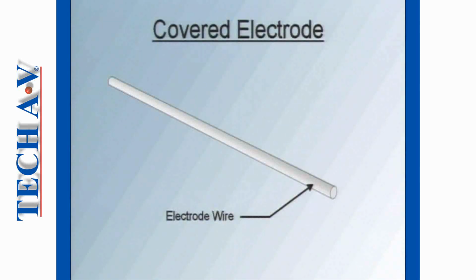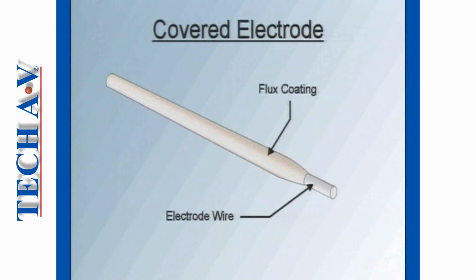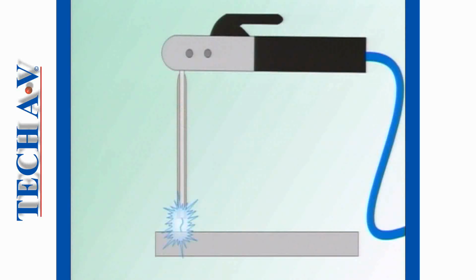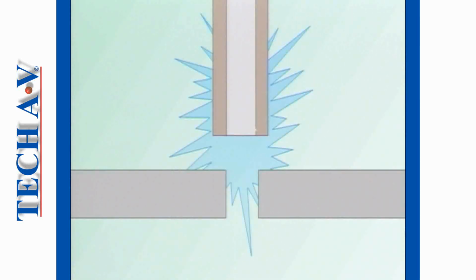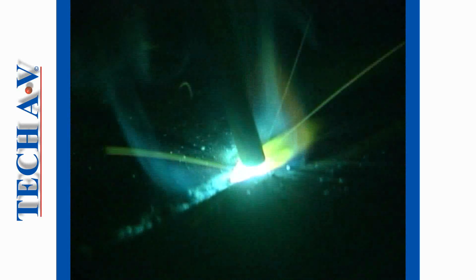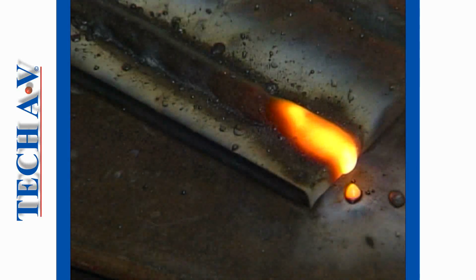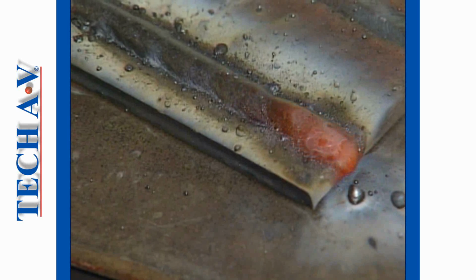An electrode is simply a length of steel rod, called wire, that is coated or covered in flux. The steel wire is made of low-carbon steel, and this serves two purposes, namely, being conductive, the wire permits the passage of the welding current, and being of similar material to the work, or base metal, the wire melts inside the arc and supplies filler material, or reinforcement, to the weld. As you learnt earlier, the flux coating burns with the arc to form shielding gas, and then slag, both of which protect the molten steel from reacting with the atmosphere.